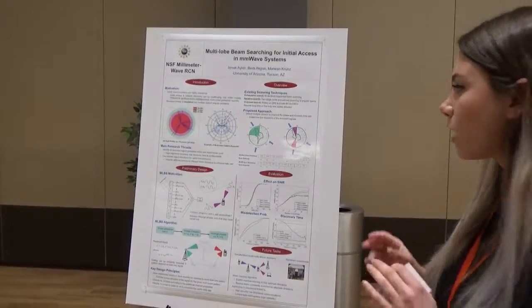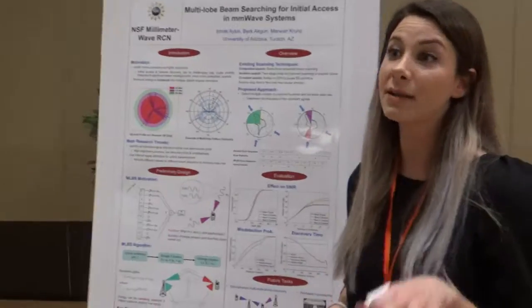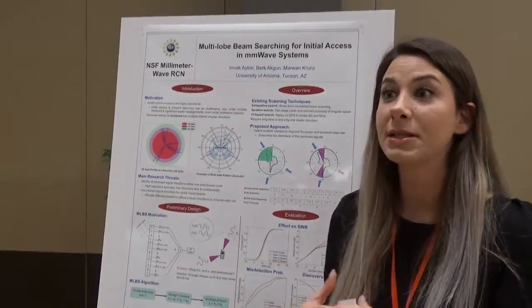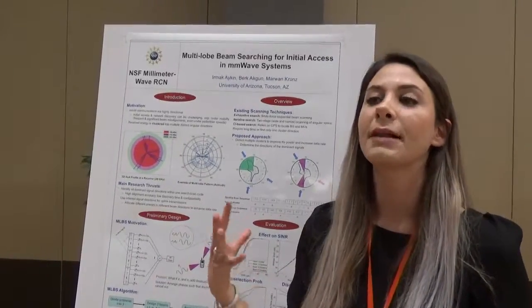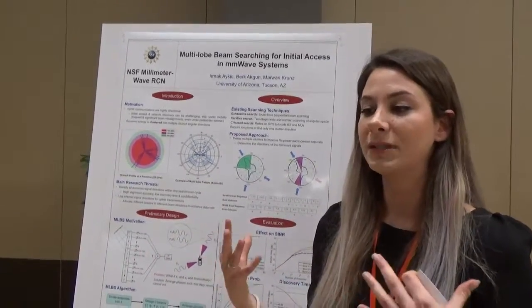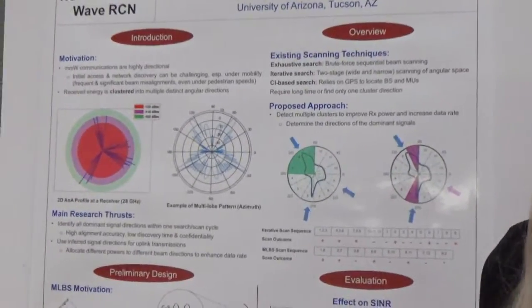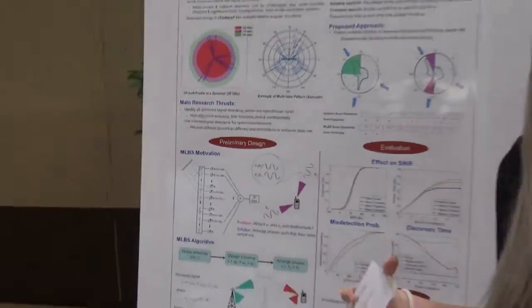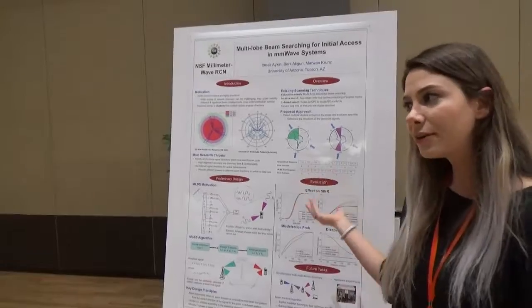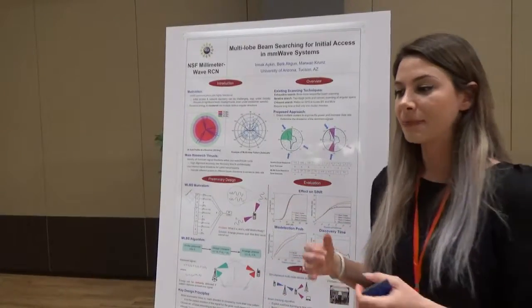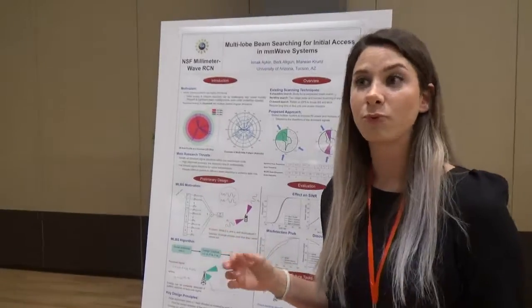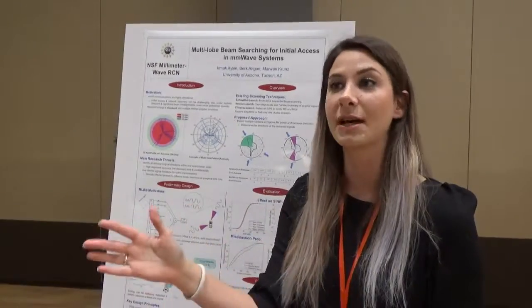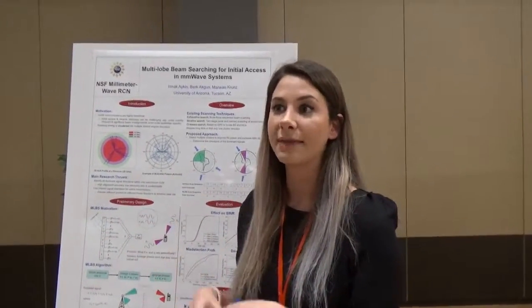Yeah, sure. So what we are trying to do here is to borrow some of the concepts of digital beamforming and apply them to analog beamforming. In digital beamforming, you transmit some pilots, and using those pilots you measure the channel so that you design your precoders accordingly. The channel that you measure doesn't really give you a direction, it gives you a combination of several multipath components. But what we do generally in analog beamforming is simply design a codebook. We do a codebook-based approach, meaning that we design a pattern that is looking into a direction, and then we simply switch that direction at each time slot to find the best direction.